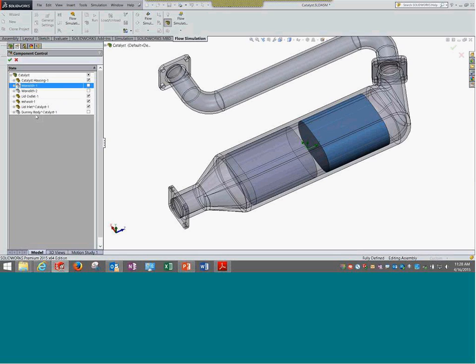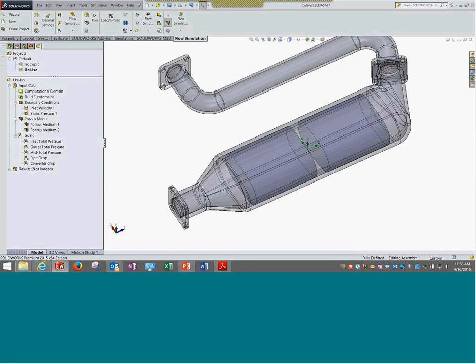First of all, we have these components which are being represented for a porous media which is going to be working as a filter. Now, the logic or the discussion that I had for the perforated plate remains here. So, porous media, apart from creating a pressure resistance or a pressure difference, may not be doing the exact job of a perforated or a porous media. In the sense, porous media may be filtering certain things, porous media may be affecting the flow directions. So that may not be happening.